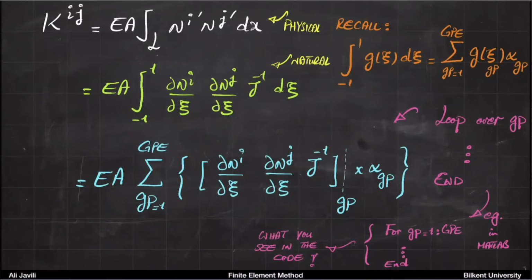So if you have a two-dimensional FEM, again, you would have some sort of a stiffness matrix and its components would be related to the derivatives of shape functions, but now the shape functions will be in 2D. And then in order to integrate that, you transfer that into the natural space instead of the physical space, and you do the summation over the Gauss points instead of integration.